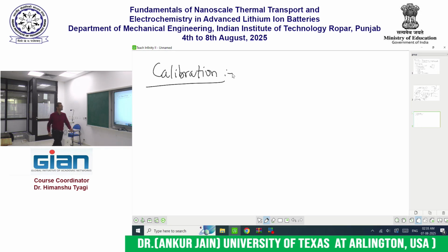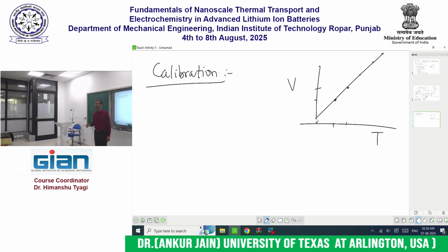So in other words, I want to create a plot of voltage versus temperature. At 25 degrees C, I read a voltage. Then I repeat this measurement at say 27 degrees C, and I repeat the measurement and I get this number. I run this calibration at a number of data points, and I have been able to get what is known as the calibration curve.